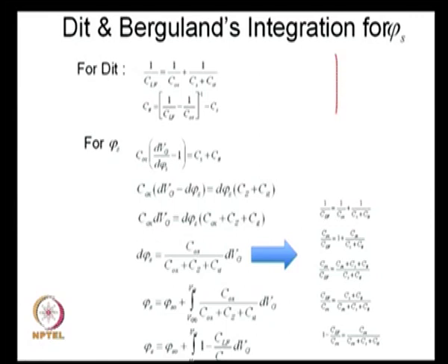I have measured the low frequency CV. Remember that in the depletion region the low frequency capacitance responded to interface states. If your high frequency was lower, your low frequency was much higher, because the slow varying signal traps can easily respond to that, and that is why I have this model Cs plus Cit. And now Cit can be written as 1 over CLF minus 1 over Cox, minus Cs.